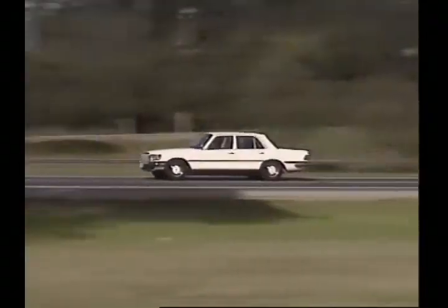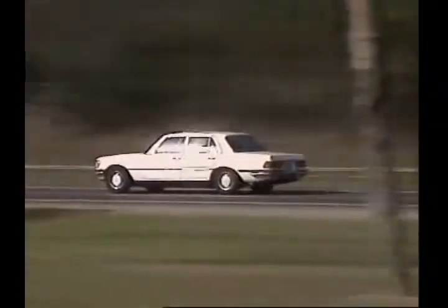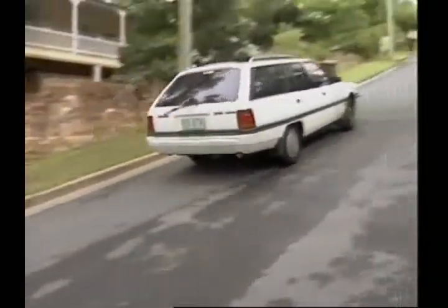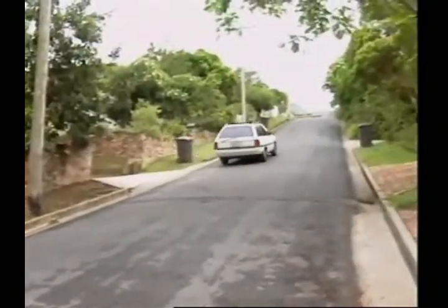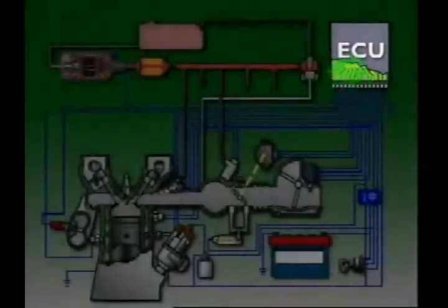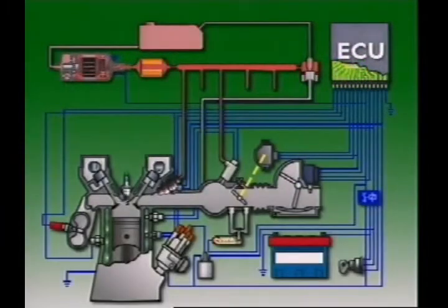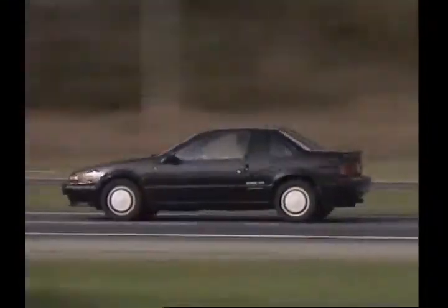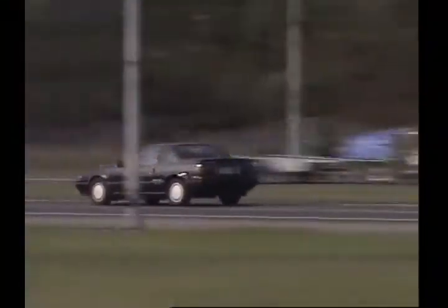For part load operation, the emphasis is on economy and drivability. At full load, it is set for maximum torque without detonation. Using the digitally stored map, the ignition point is set for each operating condition without affecting the settings for any other condition. All of this raises an engine's overall efficiency for all operating conditions.